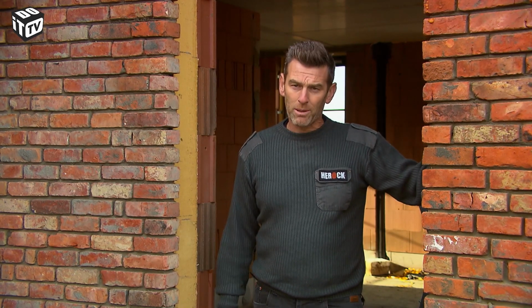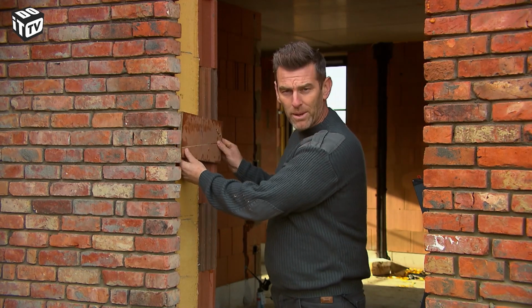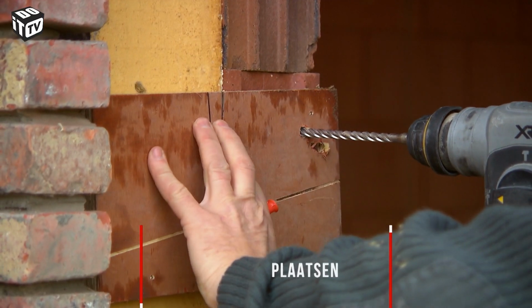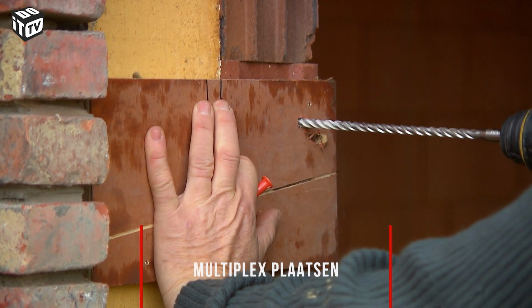In this opening, we're placing a door. The attachment of a door differs as it's heavier, and when opened, many forces are exerted on it. So, we are not going to work with mounting hooks, as we would with the windows, but instead, we are going to carefully attach plywood panels directly to the inner wall, and then securely screw the door directly into those plywood panels.